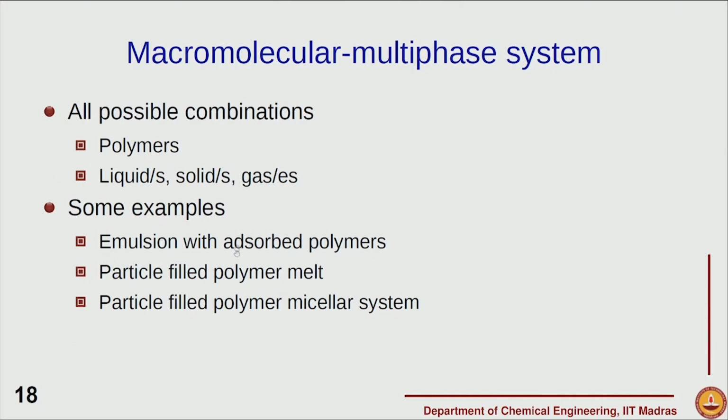We have an emulsion where adsorbed polymer is used to improve the stability of the emulsion. Polymer melts are used, as we already said, to process the materials which could be used in structural applications such as chairs and instrument covers and so on. And if you want better properties from these polymers, then we actually fill them with particles. So, these are reinforcing particles, and so when we process this material, the rheology of the polymer melt is not so much of interest, but what we should really understand is what is the rheology of the polymer melt with the particles there. And the particles interact with the polymer melt, the particles interact with each other, and if we have particles which are, let us say, rod like, then these particles may also orient due to deformation, and therefore one needs to understand the rheology and flow behavior of particle filled polymer melts for quite a few engineering applications.